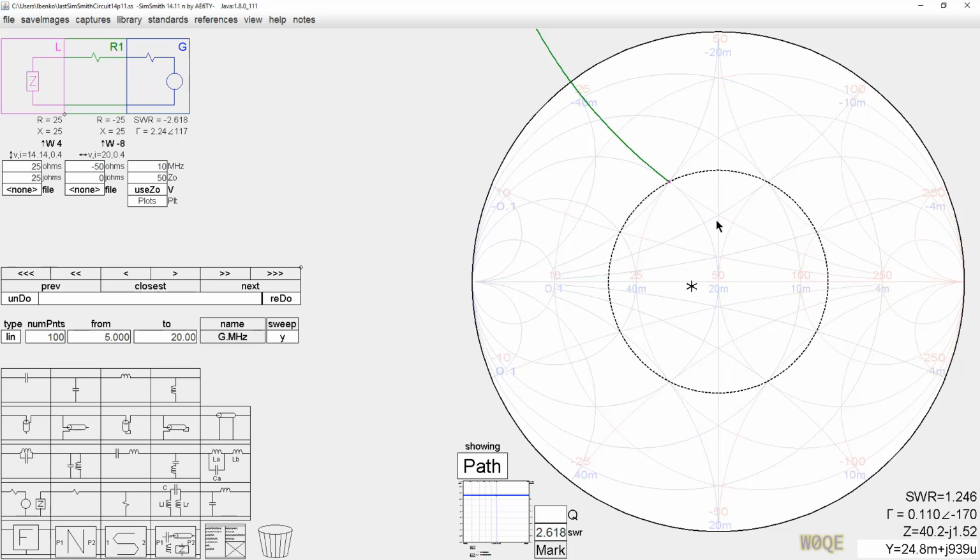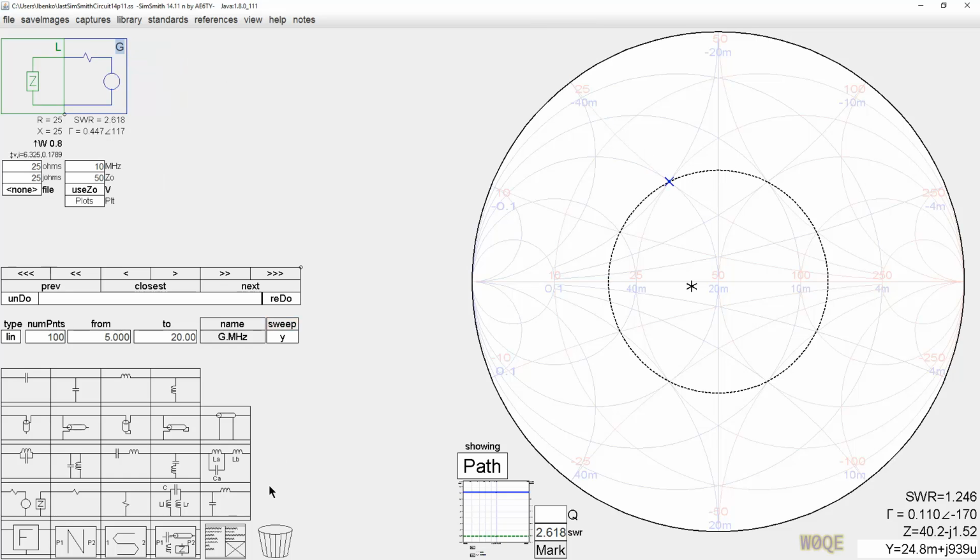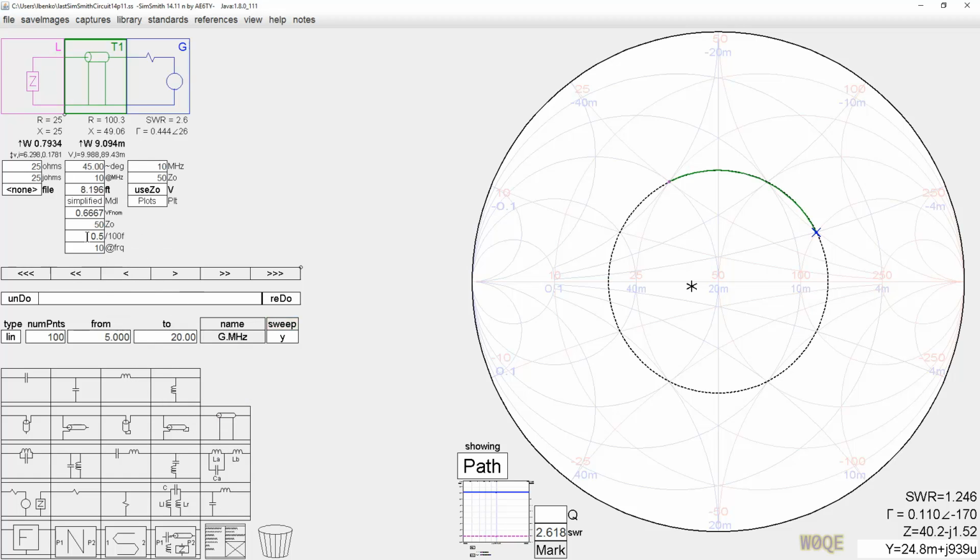The point was I used 4 more of the paths now. There's only 2 paths left. Let's add a transmission line and make it 0 loss. It follows one of the paths here. If we make it a negative length, which is perfectly allowable, it follows the other path. All 10 of these possible paths were used by the addition of relatively simple components that would be incredibly difficult to do manually. The math would be incredibly difficult to do manually.